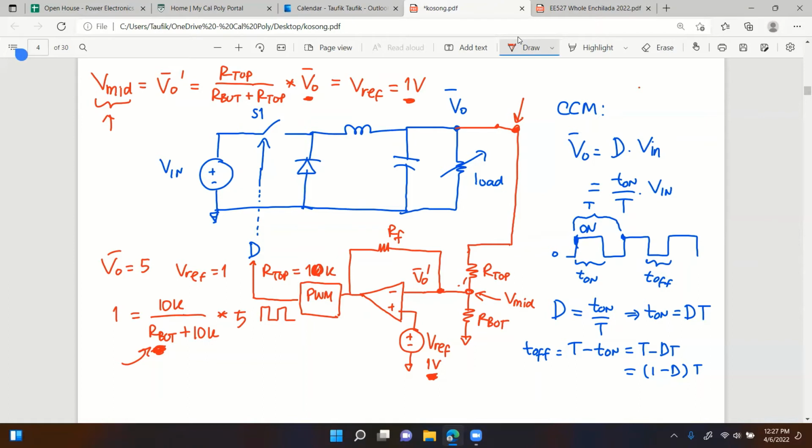Remember from 302, you have an underdamped response, which you will, because the load is typical. That happens when the load is light. When the load is heavy, meaning the resistor is very small, that corresponds to small damping, and that would cause overshoot as well as oscillations.